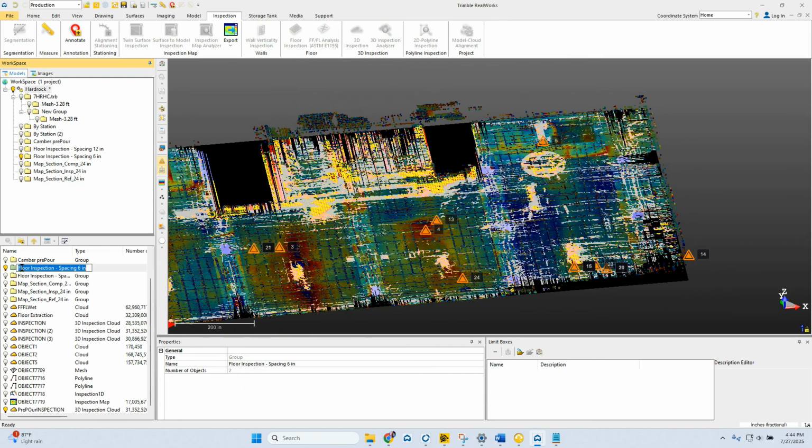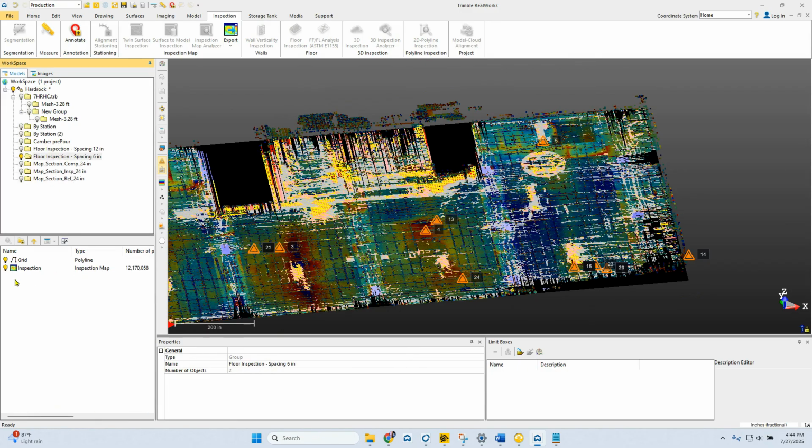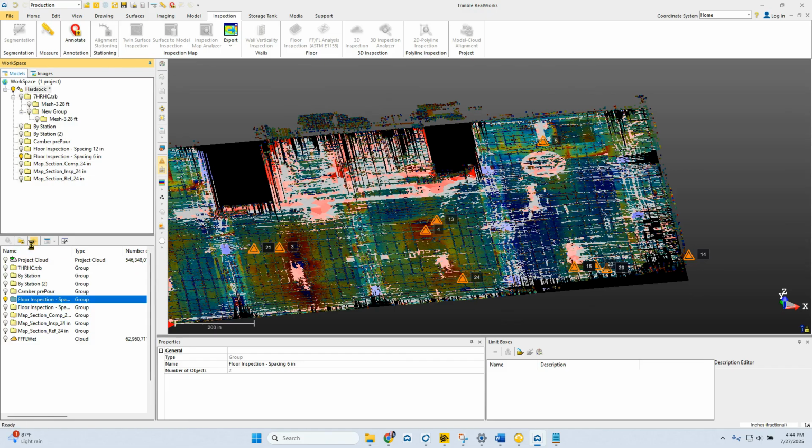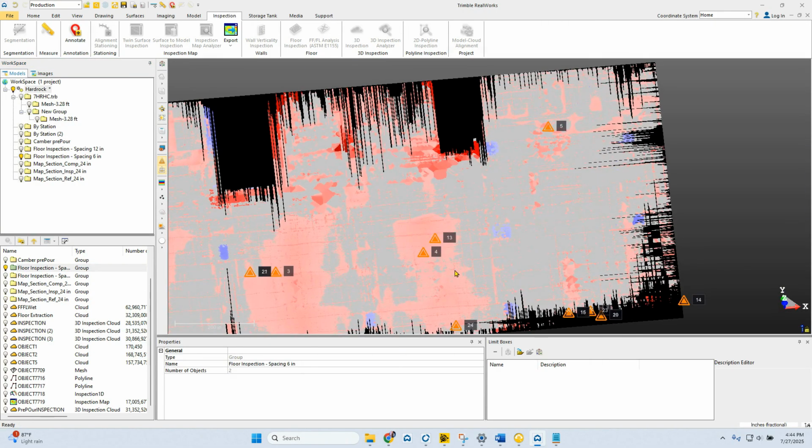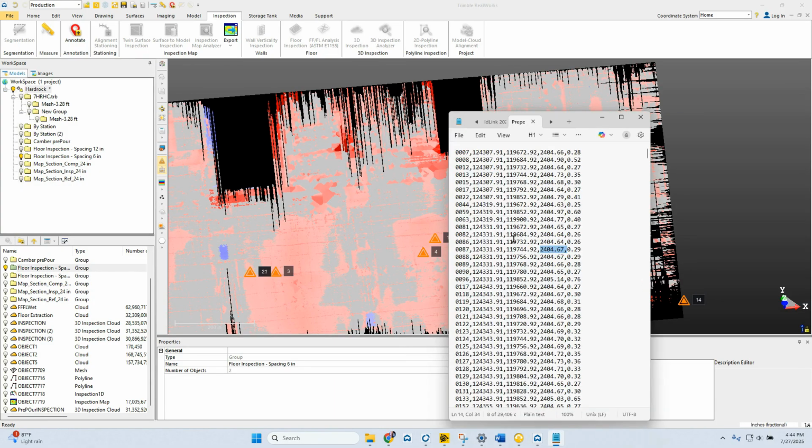Yep. And so what this will do, if I turn this off and come back one, is I can hit a reference elevation and then say anything that's like a 1/4 inch high or 1/4 inch low. I can create those same points or similar points, but a little bit better accuracy. So each one of these points is a grid line spacing of northings, eastings, elevations, and then deviation to the reference. And so that'll be created.